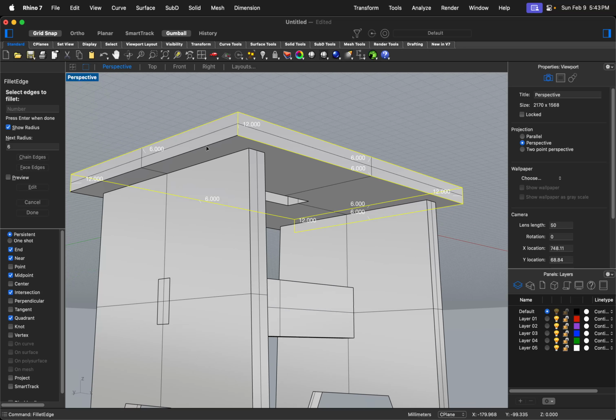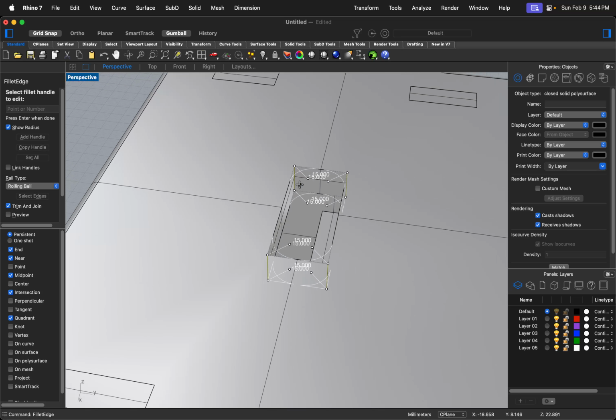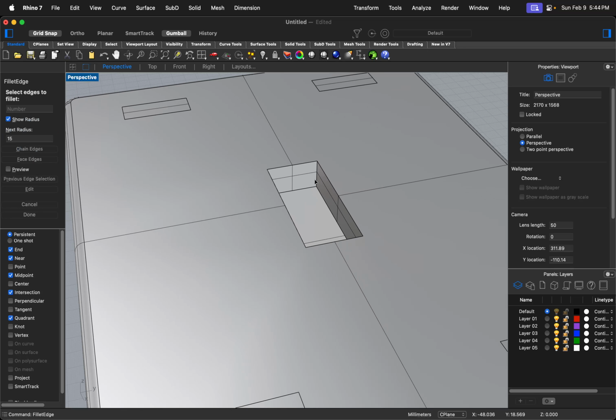Looks alright. Next, I'm going to look at the center hole here. So we have used 20 mm and beyond to open this. So I will just use the fillet here and give a slightly larger number. For example, I can give a number of about, let's try 15. 15, 15. That's all four corners. For the preview, it looks alright. Cancel and then do it one more time.